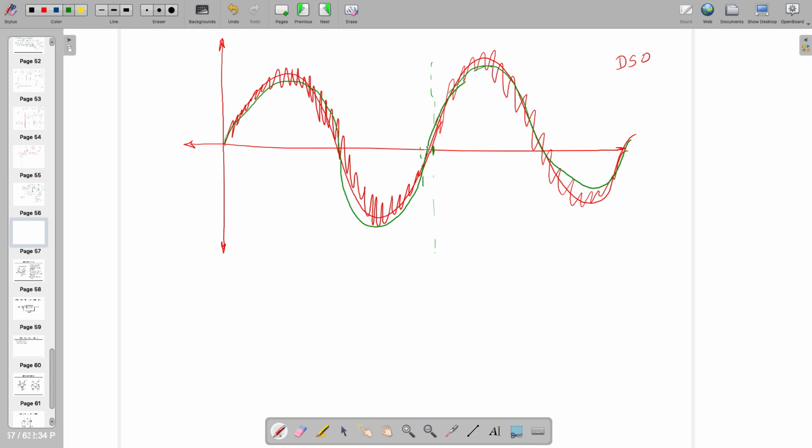So in that case, we don't take such a window which is rectangular. We are going to take another window. It might have a different look. This window is Blackman-Harris, and that's how it will take care of whatever mistakes you are making in the measurement when you want to convert it to the frequency domain. If you take the Blackman-Harris window, you will get less leaky output.